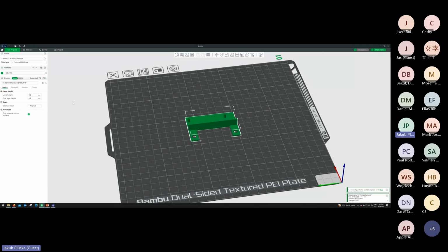However, you may change a lot of things. So like I said, you may have a specific profile for the filament with different temperatures. So it's very useful to adjust to the correct ones, matching the specification you have on the box.